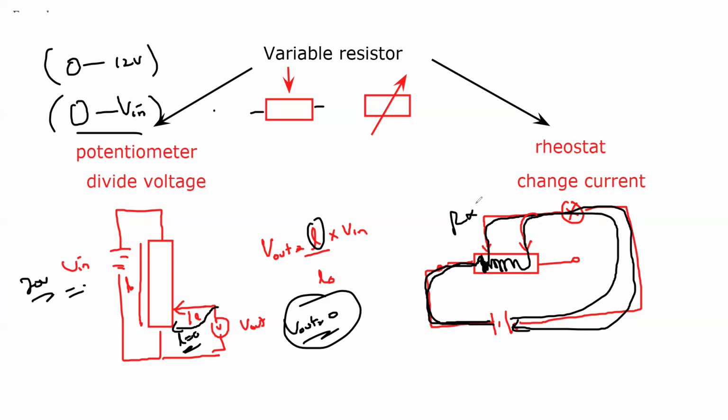So resistance is directly proportional to length. The longer the section of the wire of the variable resistor the current has to pass through, the greater the resistance of the component. But in a rheostat, we can never have a voltage of zero across the device, across the component.